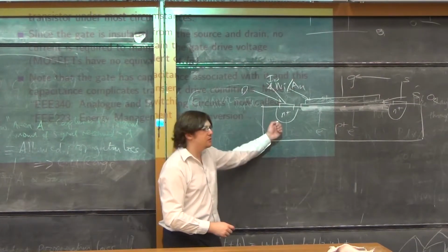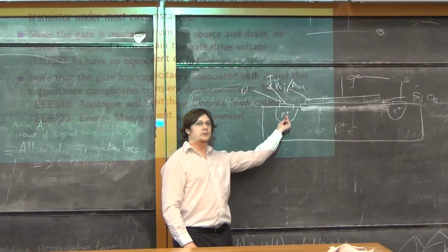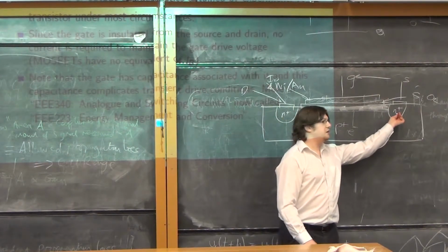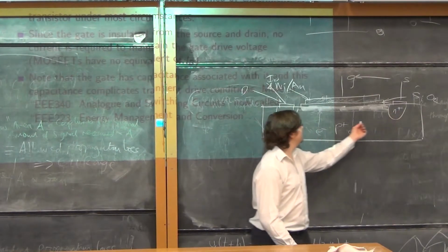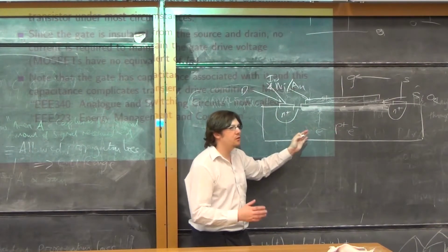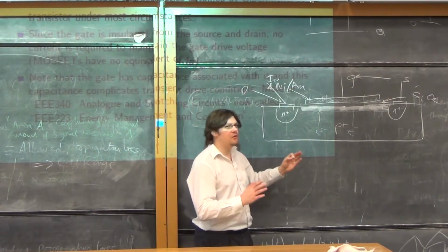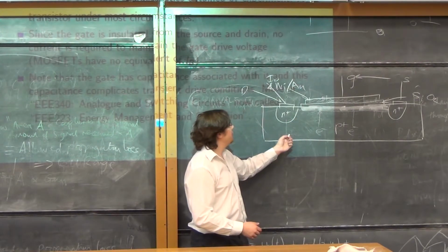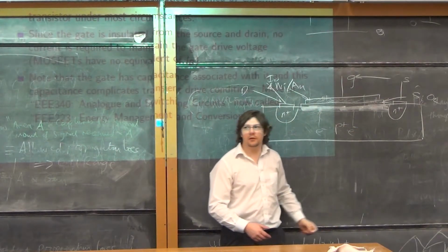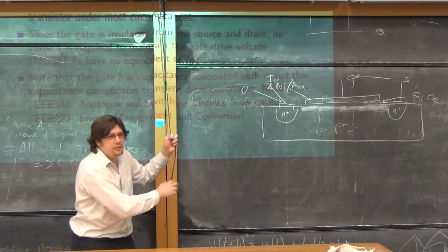Once we've achieved that, it will be easy for current to flow from this electron-rich environment through our inversion layer into this electron-rich environment. So what we're really doing is reducing the, well, you can't really call it reducing the resistance, because, well, we are a bit, but I don't like that. What I prefer to say is that by attracting electrons, we're creating a channel through which the current will flow. If you're not keen on that, don't panic, it'll be coming back in second year.